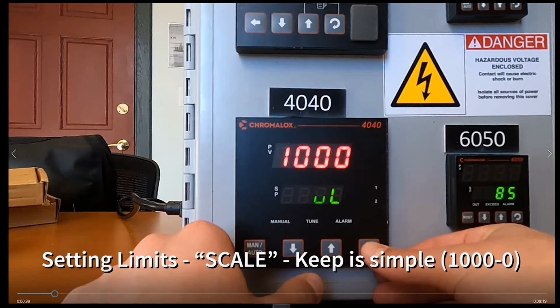If you are using a thermocouple, it will usually default to the temperature range of that thermocouple type. So if you ever go in here, and you're curious why for this controller it was already at 1,000 to start, and for another one maybe it's at, what's the K type, like 2,100 something degrees Fahrenheit, that's why those numbers might be different when you get a new controller.